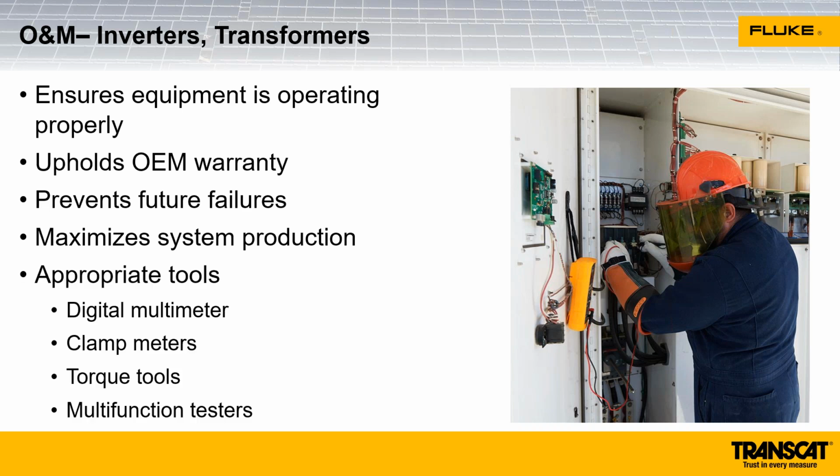We use a suite of different tools when doing operations and maintenance on inverters and transformers: digital multimeters, clamp meters, our torque tools, and multifunction testers if we're doing IV curve testing of our inverters. We again stress this over and over, but it's really important to ensure that we have tools that are rated for the category, the environment that we're working in, and the voltage of the equipment that we're working in.